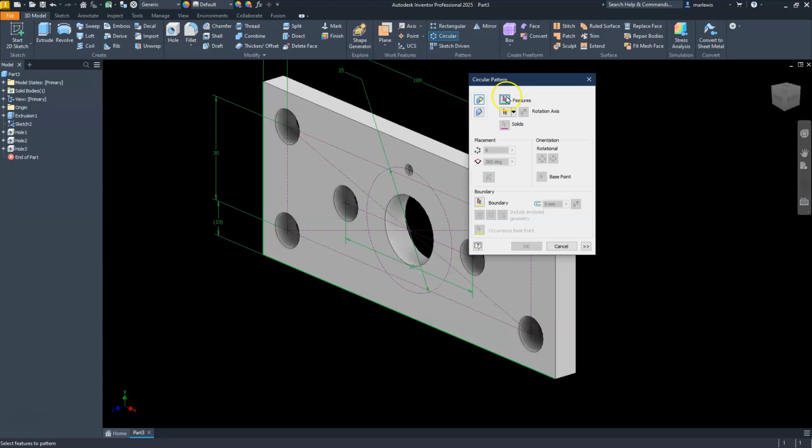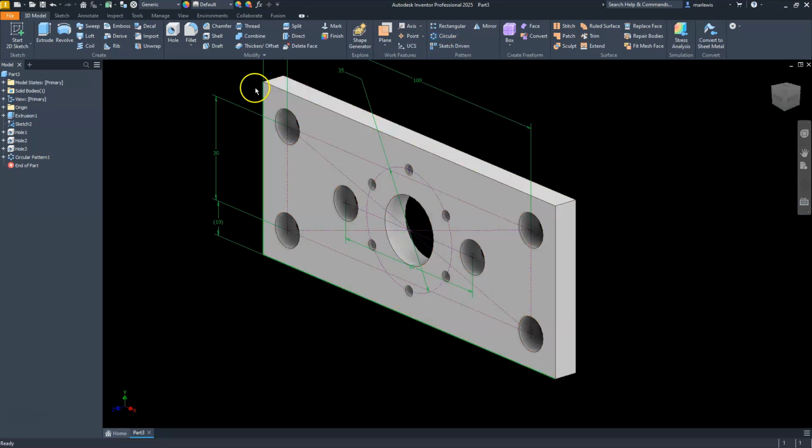Next to last step we need to do is go ahead and do a circular pattern. So I'm going to select the feature first, which is going to be hole number 3. I'll select this arrow, and then it's saying, give me a concentric reference or something to go around. Now I can use the Z-axis, or we can simply select this circle on the inside of here, and then it can figure out the axis of that, and now it'll count out and show you the rest of those holes that'll be created. Let's go ahead and hit the OK button.